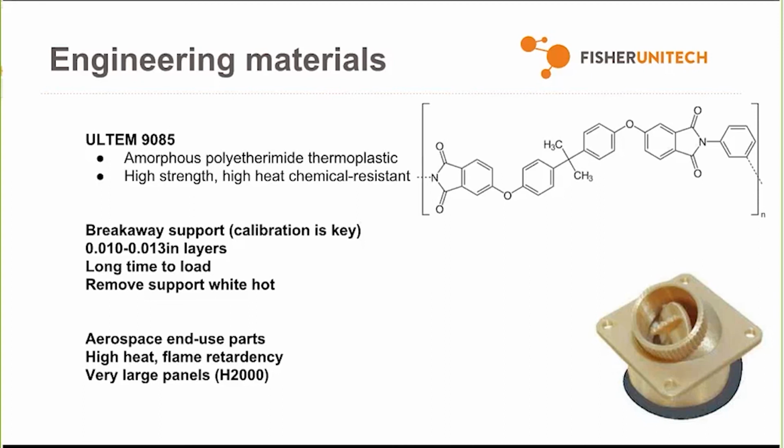So it helps to eliminate any slop, to make sure that you're getting material properties that you were promised, or accuracy, excuse me, plus or minus 0.005 of an inch. And the reason is that you're bringing this oven up to about 400 degrees Fahrenheit, and that takes a while on its own.